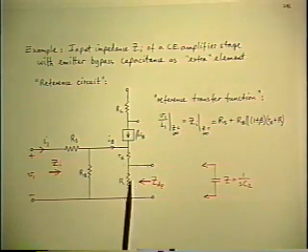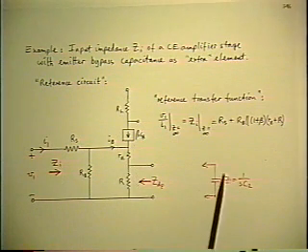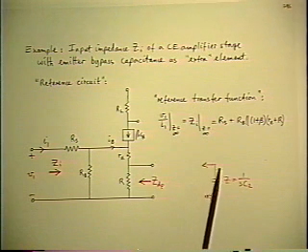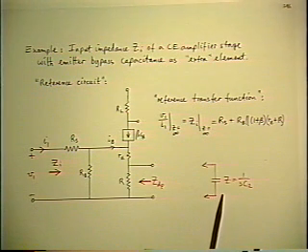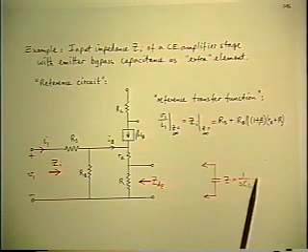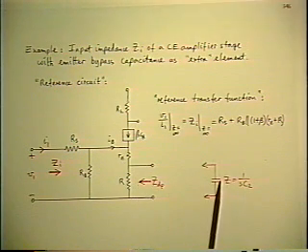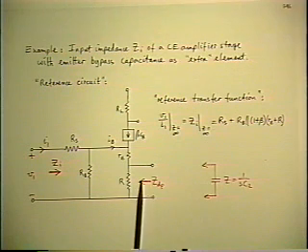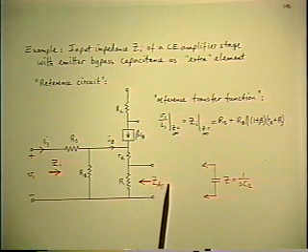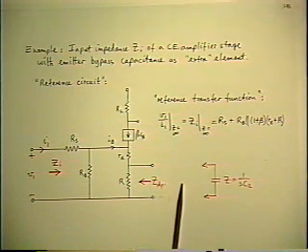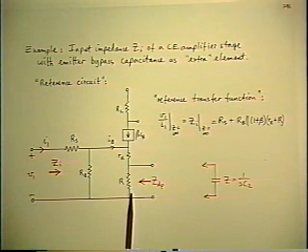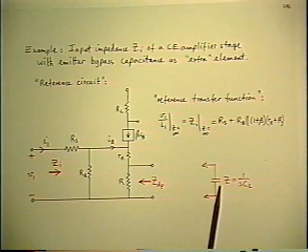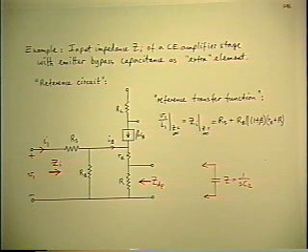So here's the basic reference circuit. The objective is to put a capacitor across those two terminals, so I've just drawn the capacitor off to the side. That's just a reminder that ultimately that's what's going to be connected. But in order to do that, we have to calculate two driving point impedances. So I've simply represented that as the ZDP looking in at the terminals where the capacitor is going to go. Okay, we have two calculations to make.